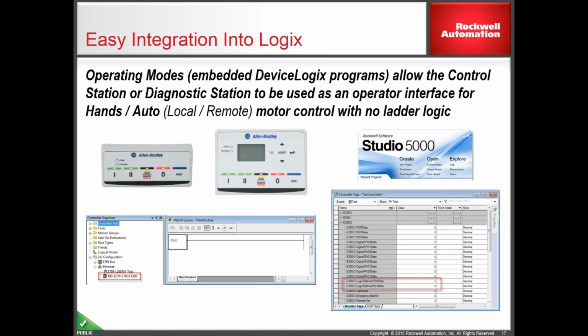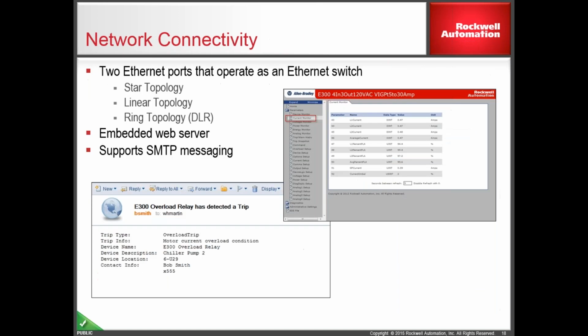And then one of the other features, I don't know if you're going to discuss it later, is the DHCP port persistence with our static switches. What that'll do is make it a little bit easier. You can set up your E300 for DHCP and it'll assign the IP address that the existing one had, and that way all you really have to do is plug in a new E300. It sets the IP address, downloads all your parameters, and you're up and running again. So for any type of maintenance or repair issues, that's a really nice feature that we've got.